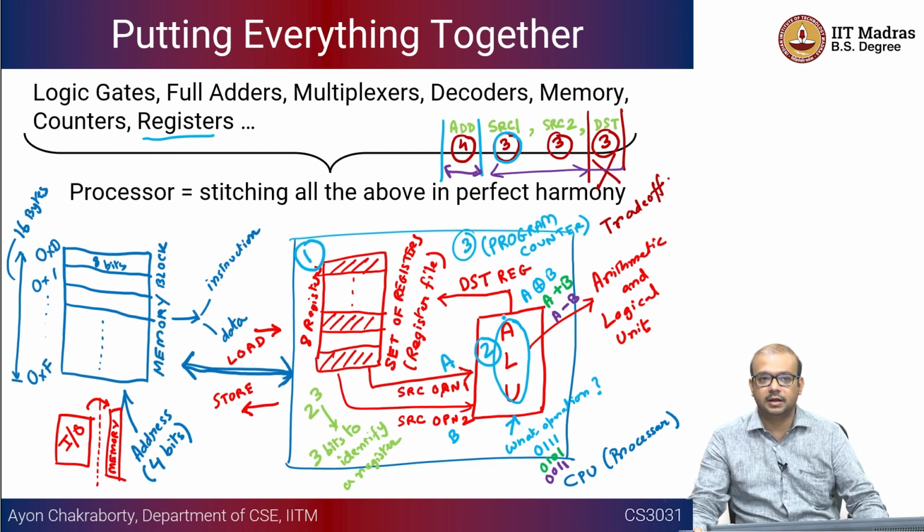It's very simple. A XOR B XOR C gives the sum, and the carry is AB plus BC plus CA, right. A and B are the two bits you are trying to add, and C is the carry in, right. And you can do this full adder for a 4-bit, 8-bit or 16-bit adder based on the size of your data. Okay. So conceptually it is very simple.